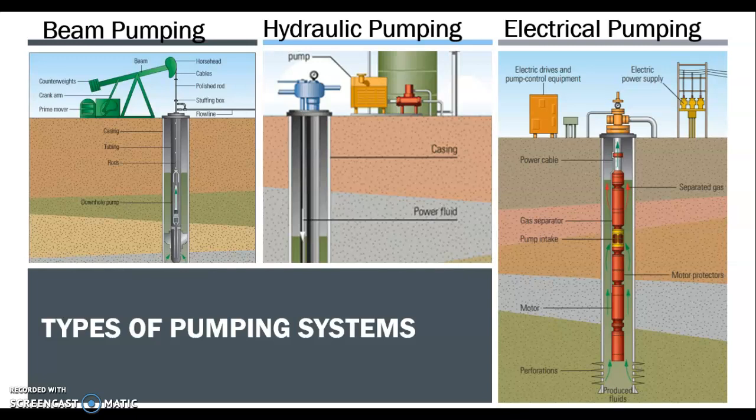And lastly, we have the electric submersible pump system. This system has a centrifugal pump in the reservoir. In this system, the pump is connected to a long electric motor that, with its several blades, is able to move the oil within the well. An artificial lift is applied by moving the blades on a pump shaft that creates pressure on the surrounding oil, therefore forcing it to the surface.